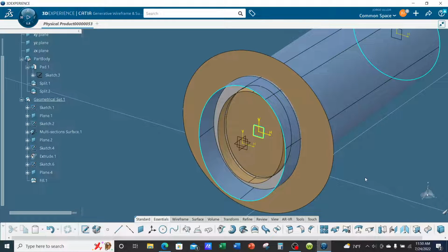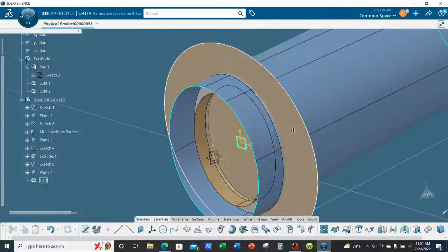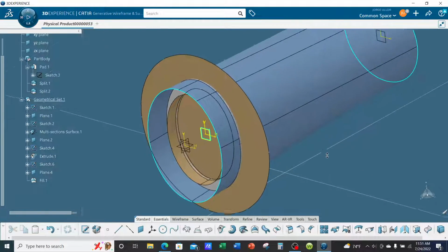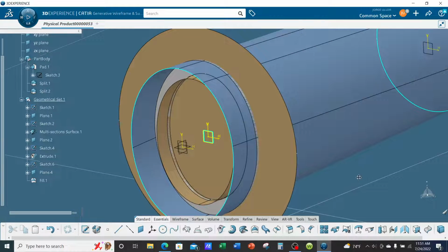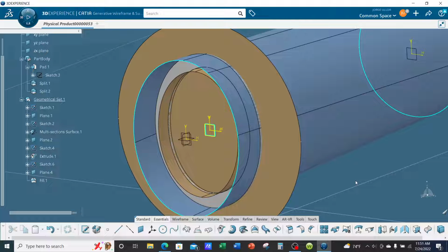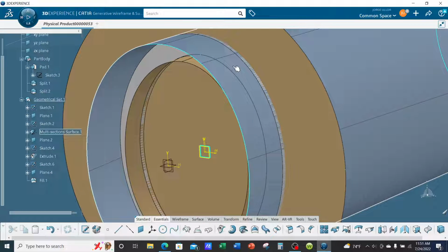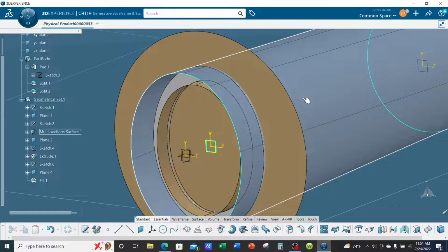Okay, so let's say that for the flanges, let's just keep it at 1/2 inch. Typically it's not the same thickness. Typically a stress analyst will give you the thickness of the flanges and the thickness of the web. Alright, so here's what we're going to do. We're going to also offset the IML surface inward by 1/2 inch. So let's say the stress analyst tells you, hey, we're going to make these flanges 1/2 inch thick also, just like the web.